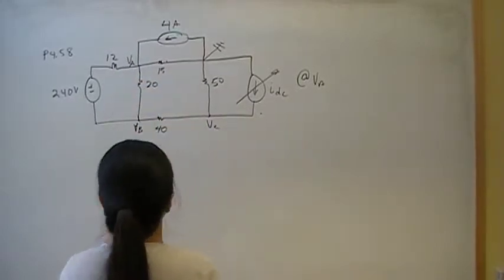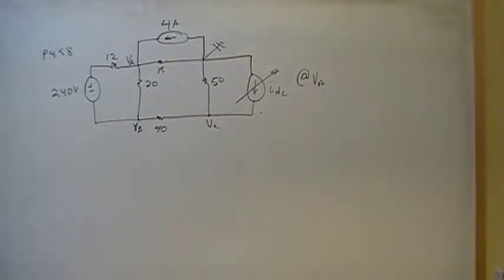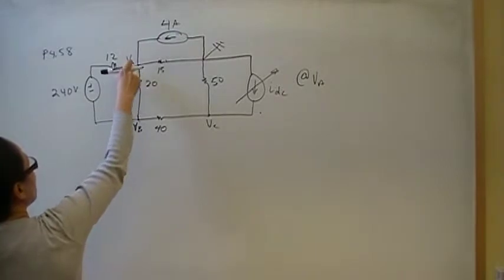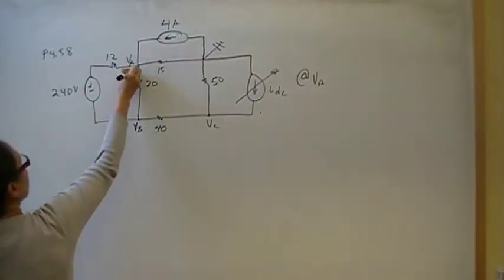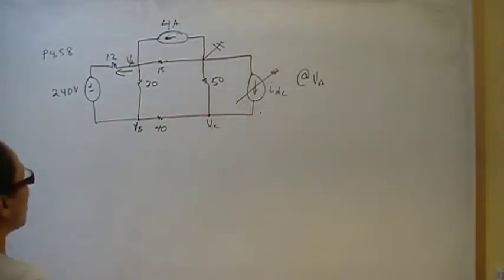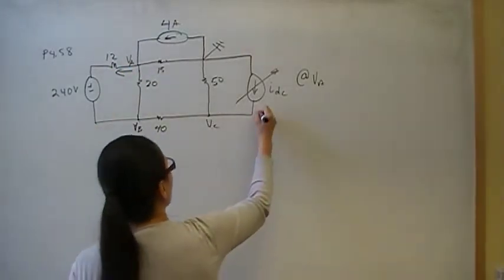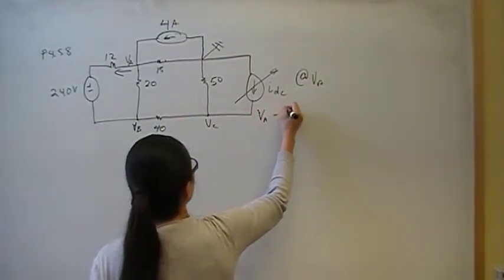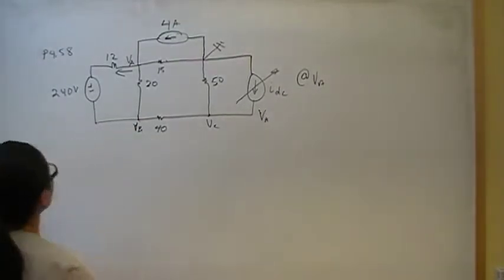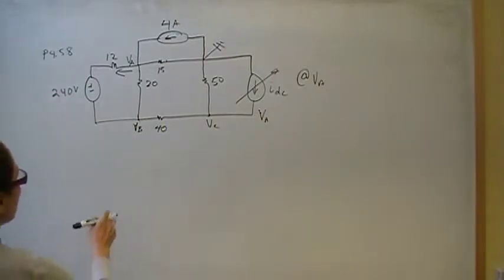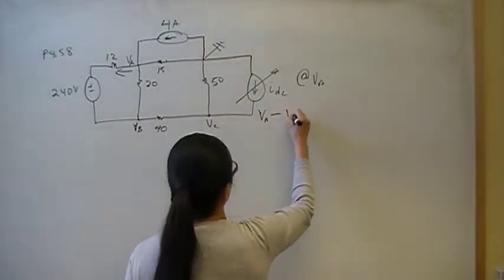We're summing currents, and remember current is voltage over resistance, so it's going to be this voltage minus the sum of these voltages, right? So this current is what we're writing, so that's going to be VA minus, okay, so what are we minusing? We're minusing this voltage and we're minusing that voltage, so minus VB for sure.